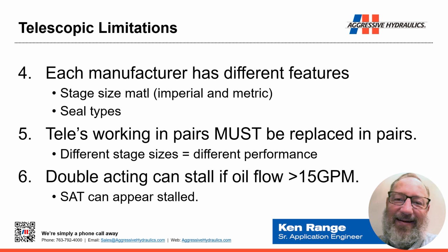At the same time, if they're doing startup and they start at low pressure and they just gradually creep up that flow, it is possible for the oil inside a double-acting telescopic to simply circulate through the fluid routing paths that are internal to the double-acting tele and that are associated with each stage. We'll look at those in just a minute. But it can just simply flow fluid through those oil paths, and yet the cylinder never moves.